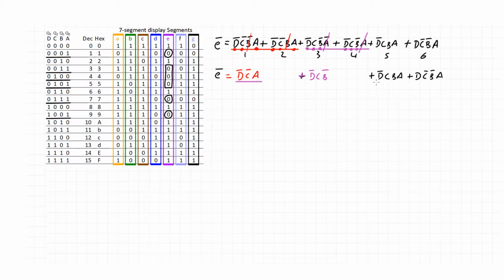Now with this term and the third term, they have not D and A in common. Then we have not C or CB. So that is the absorption law. Not DA is common to both. We have not C or CB. So it's the C that we get rid of with the absorption law. So then we just multiply out to what's left.